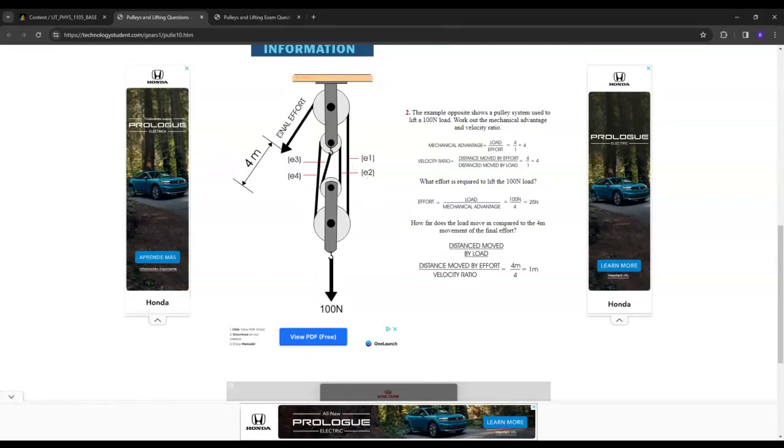So you have to pull a lot more rope out of the system than what this is actually going to move up. If this were to go up by, say, 8 feet, then you'd have 8 feet of slack, 8 feet of slack, 8 feet of slack, and 8 feet of slack. All of that you'd have to pull.